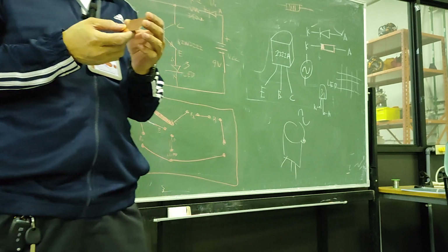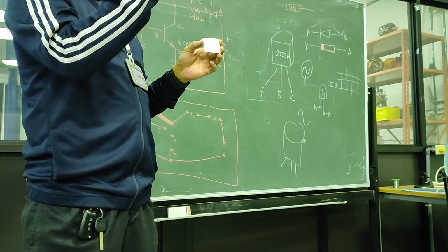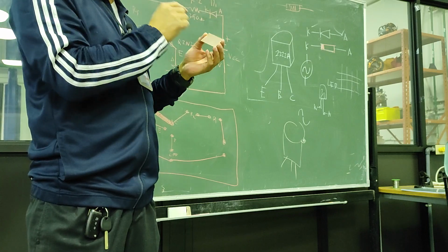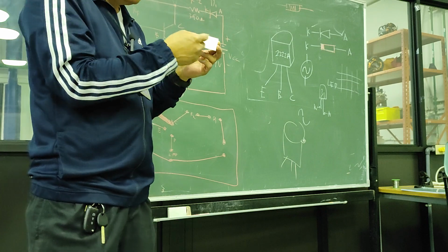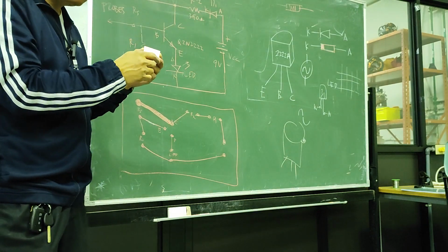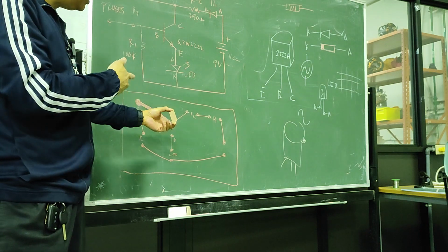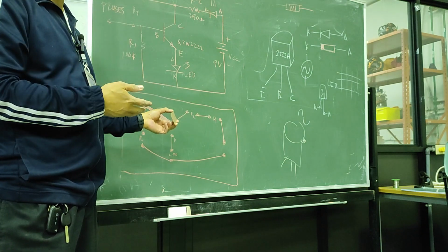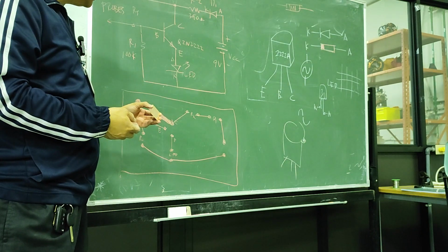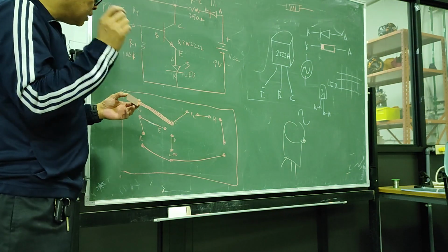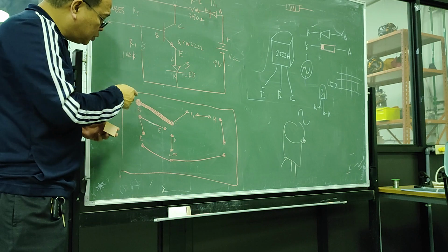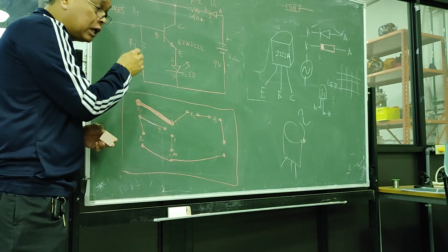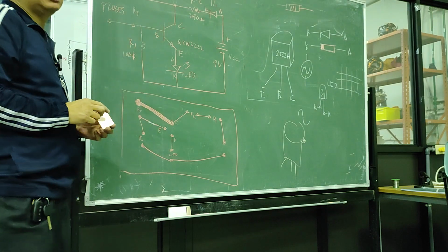Okay? So now, what you will do is, do you have a pencil? No. Okay, anyway, you have a pencil or pen. You will now try to design the layout from this circuit. You can make this a reference for your artwork or your layout. Again, as I told you last time, as much as possible, make the pads bigger and make the terminals thicker.